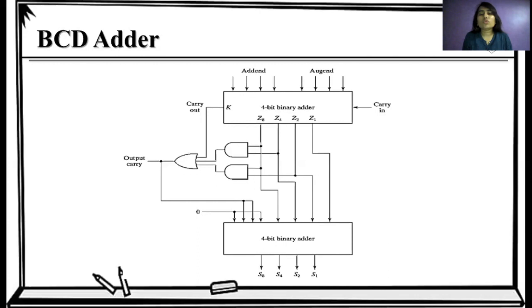The 8421 represent weights, and we also have an output carry K. We have an invalid BCD number for addition of 4 bits if this K output occurs. So this is given as a correction equation for the next binary adder circuit for correction.